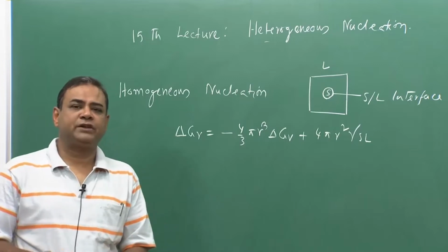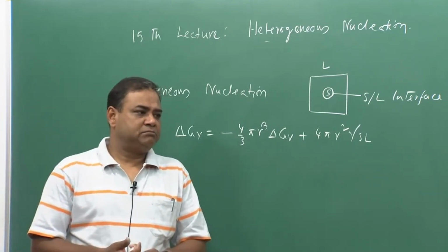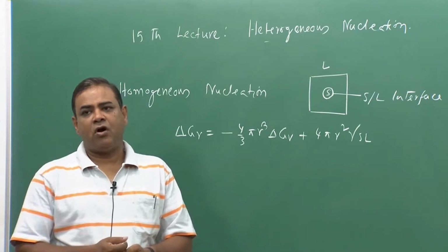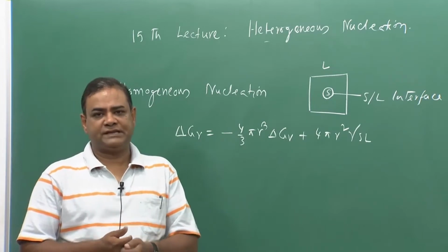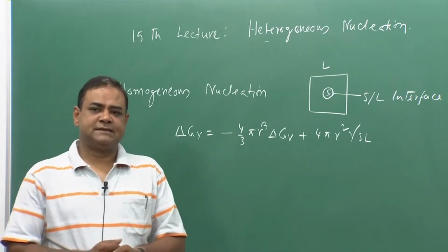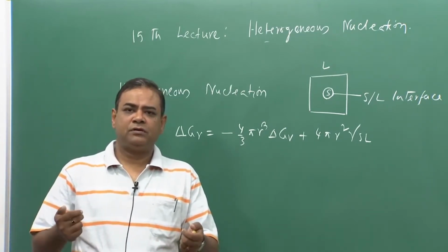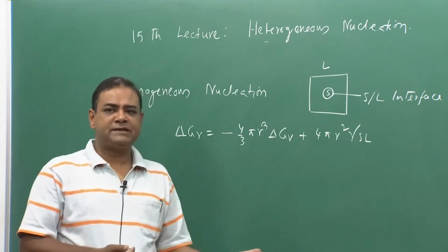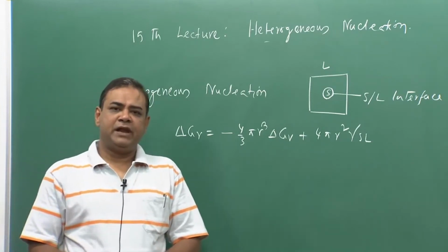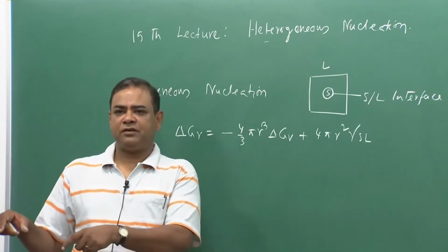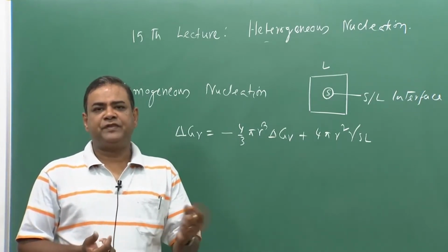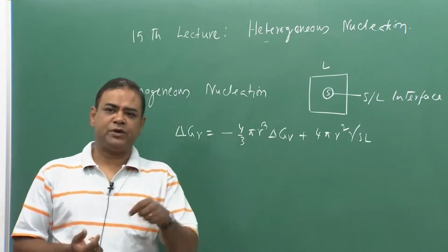For example, if we would like to form, let us say, engine block or engine head, or let us say manifold, exhaust manifold or clutch housing. So, those are auto castings. So, what you have to do? You have to melt the metal, and then also you have to create a mold, and inside that mold you have to also place core in order to make hollow parts in this casting, and then you have to pour that liquid metal into the mold.